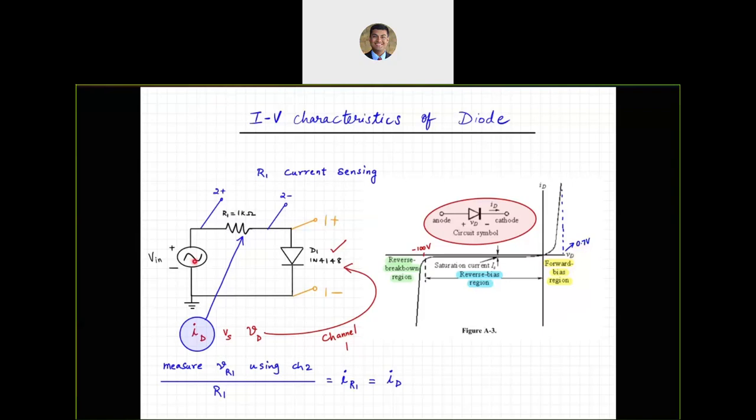If we have, say for example, 0.1 volts from the source, the diode is off and no current flows in the circuit. So it is going to require 0.7 volts from the source to turn on, and after that we can find out what the R1 is going to be.